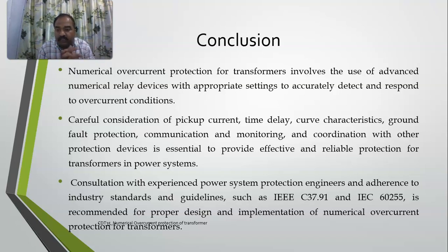So you can consult with engineers, electrical engineers. There are so many guidelines which are available. The IEEE codes are there, IEC codes are there. You follow those codes when you are implementing this overcurrent relay. Okay. Numerical overcurrent relay protection is important for transformers to protect it against incipient faults and also internal faults. Okay. So that's it from my side.